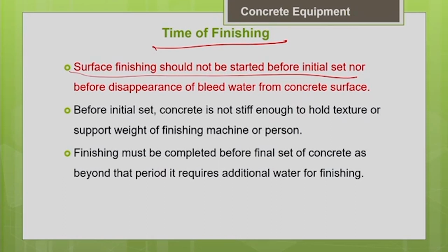Because your concrete won't be able to receive the texture you are trying to offer. If there is some water on the surface and it has not dried up, it should have the strength to support the person who is standing for doing the finishing operation, or the machines which are going to be used for the finishing operation. That is why we should not start the finishing operation before the initial setting of the concrete.